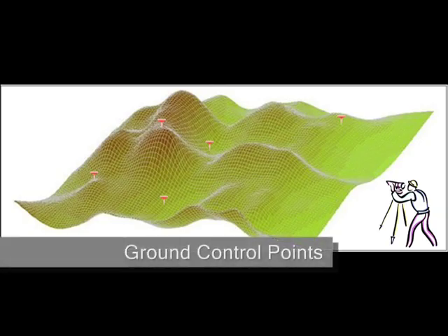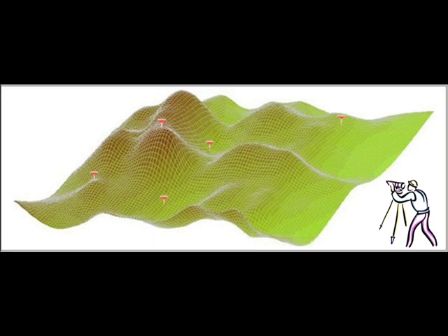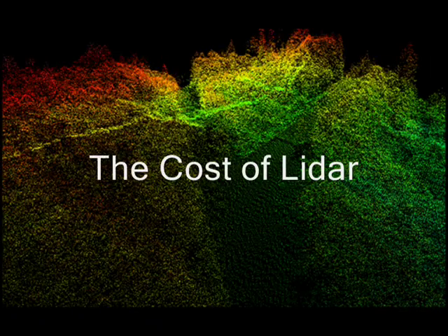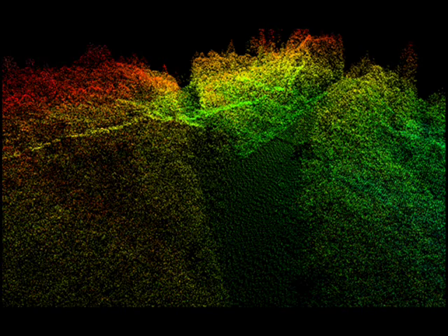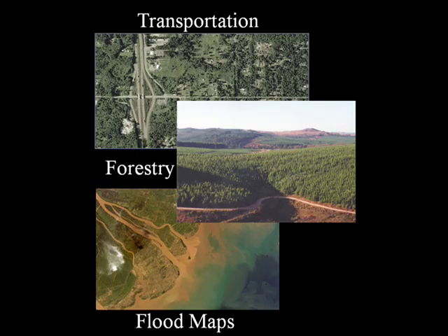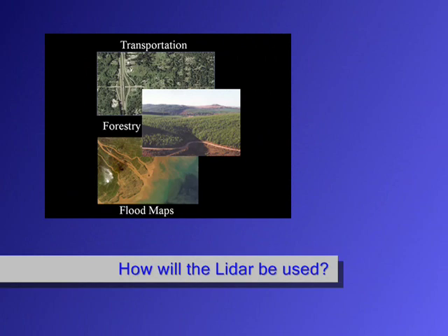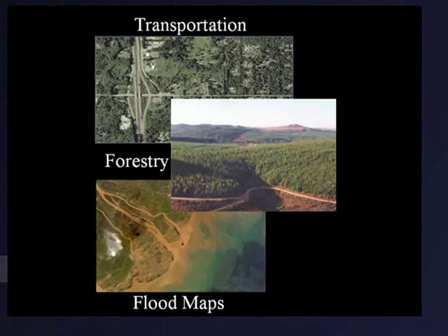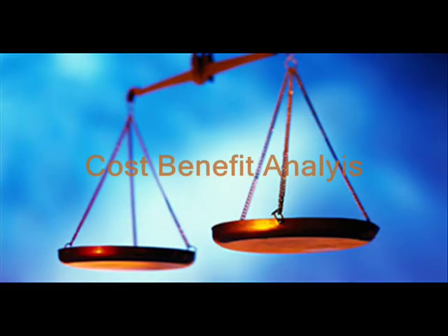To determine if the LiDAR data meets the required quality specifications, control points are assessed in the project area and compared with the LiDAR return values. Because of the many varieties of LiDAR data, products, and applications, its cost may vary significantly from project to project. The most important question regarding LiDAR's cost is how will the data be used? LiDAR purchases should be based on a cost-benefit analysis.